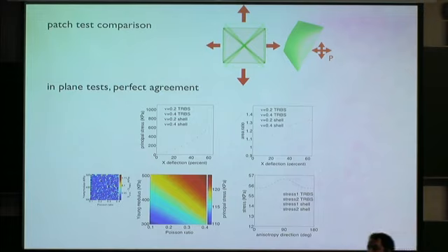Right. And the shell element there, the planar elements, they don't have any thickness. Yes. And when there is a junction between two elements, there is nothing to stop them from, I mean, at the junctions you have no bending energy.